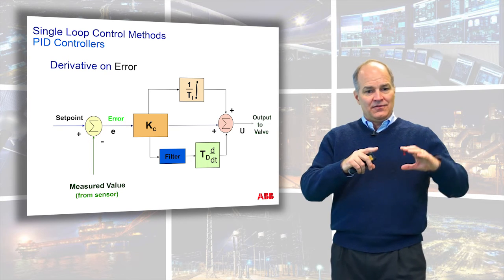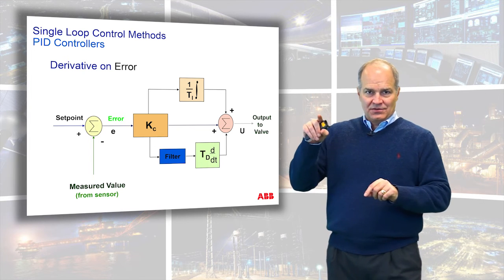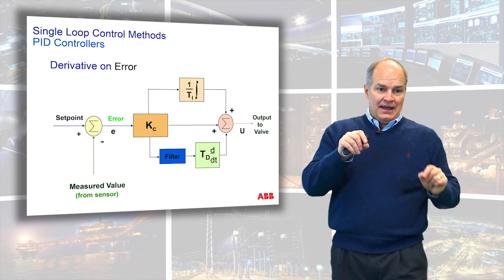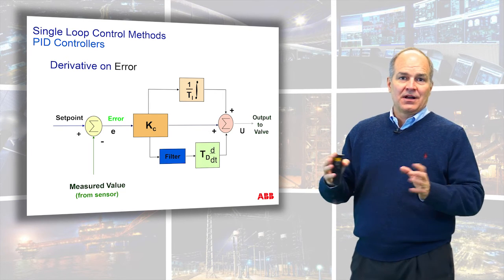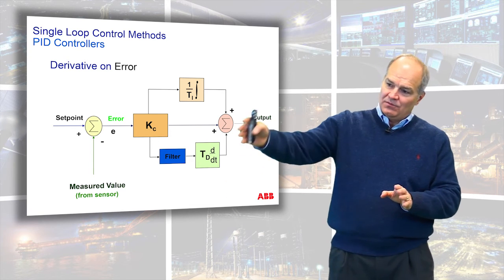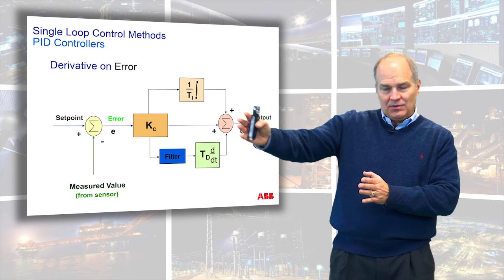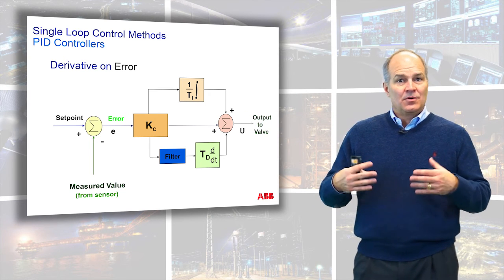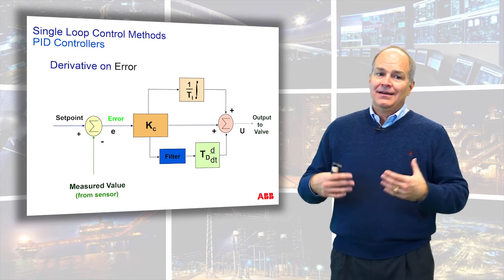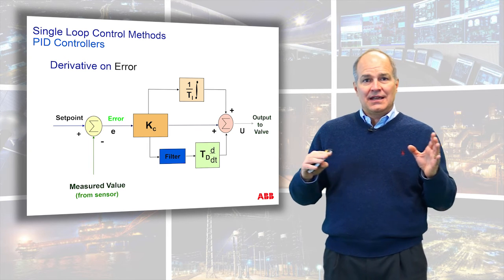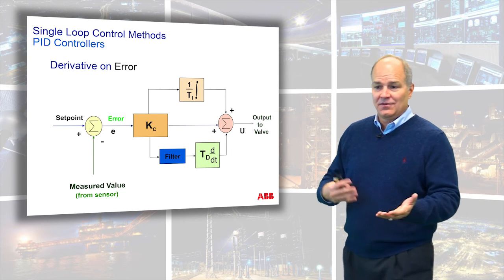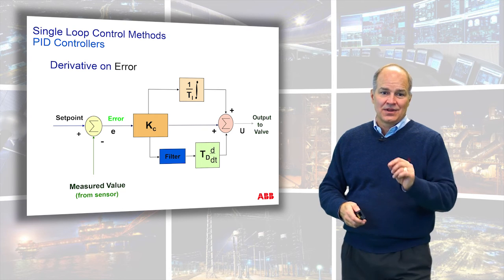I was trying to envision, if you can imagine, the points, like I drew earlier, a point, and then extend the slope on every one, and then if that represented how the process moves, your derivative is probably going to work. If you have a real slow move, remember I talked about the slow moving road? A derivative would predict where you would be if you didn't do anything. So the slower and more predictable the measurement, derivative has a chance. When there's a lot of noise, then you put a great big old filter on, but a filter doesn't just take out the noise, it actually slows the process down. So it's almost a wash. If you use derivative with a derivative filter, it almost doesn't do anything. That's why you have to be careful.